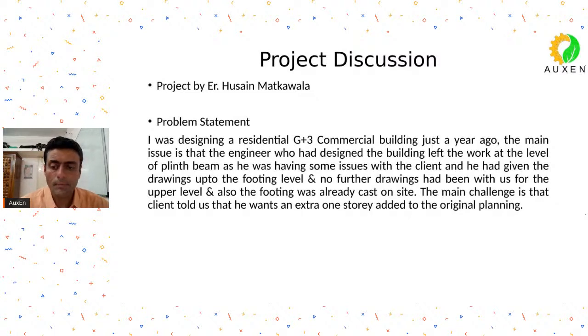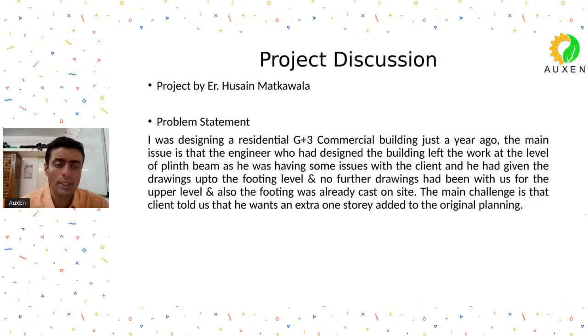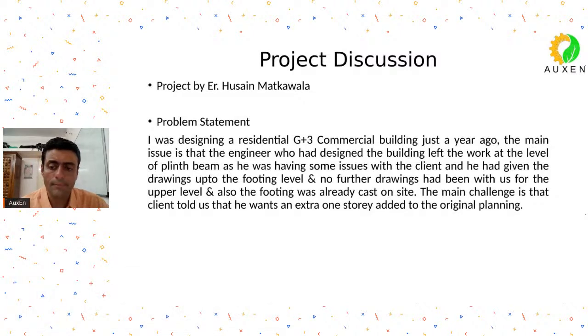So in this case also, most of you have given a correct approach to this problem statement. What Mr. Hussein did, because he had written us about the solution that he had adopted, is that they did the analysis first. After doing the analysis, they figured out that yes, the footings were insufficient in size in the plan area. So they had to excavate till the footing level. They had to go for an increase in the plan area by rebarring, and then they had to do some column strengthening also till the plinth level, and then they could proceed. So all those things they had to do in their case also. So most of you gave us a correct approach for this project.